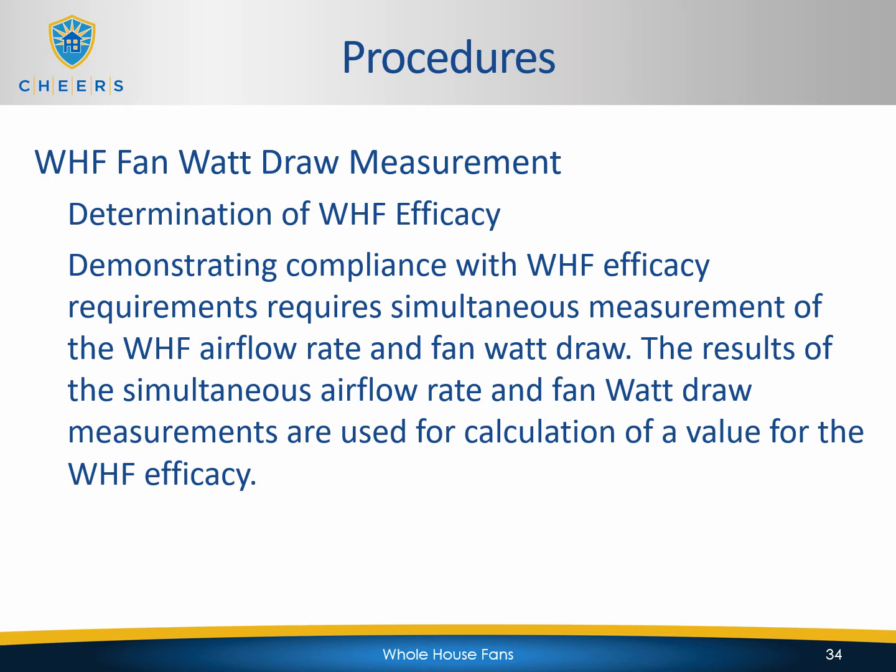Now these can't be done exactly simultaneously. You can't be taking your airflow measurement at the same time that you're doing your watt draw, just because you're a single person, but they need to be done at the same time. So you're going to set the house up, get everything running, measure your airflows, and then immediately leave everything as it is with the whole house fans running, and use whatever method it is to measure your watt draw. You need to do it as close to each other as possible so that it's tested under the same conditions.